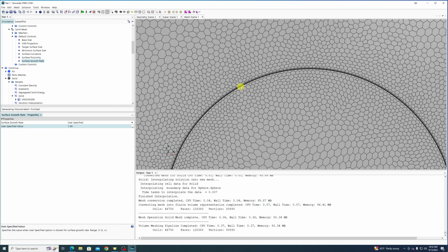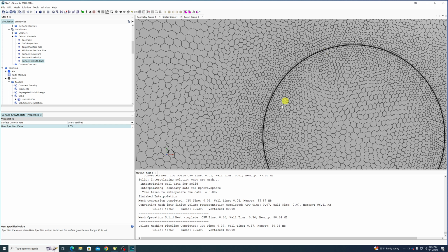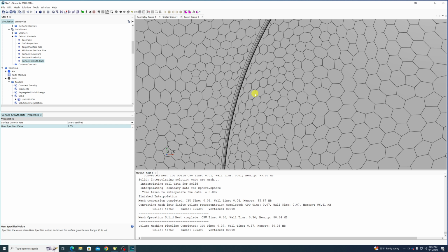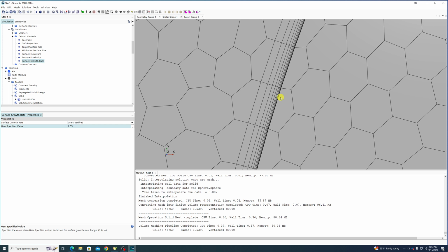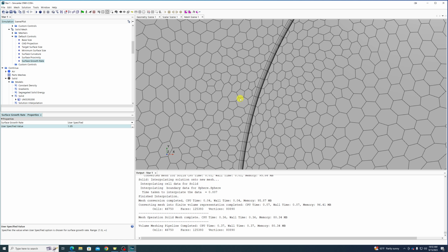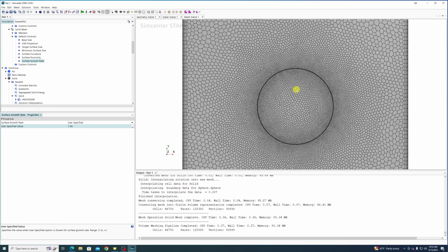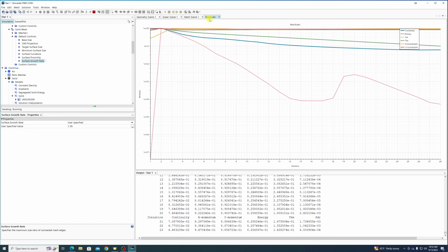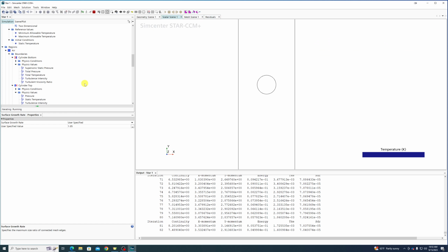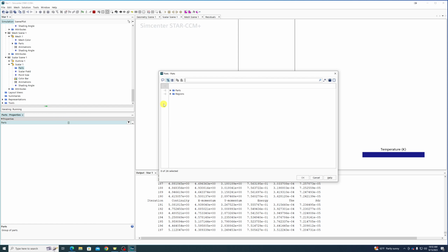So it's very, very close. These are basically the same mesh at this boundary. That's actually kind of important. You want the mesh across an interface to look as close to exactly matching as you can reasonably get it. This is really good. And then it can diverge a little bit further away. So now if we hit run, it should run for starters. And we're not looking at anything. Oh, because there's no parts under our scalars.